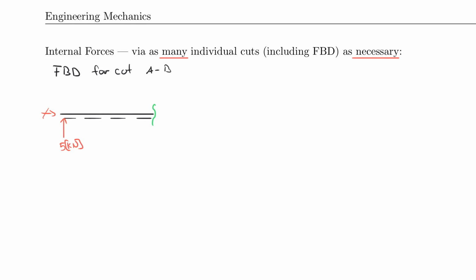But then there was no other force on the system. Remember that? There was no force except that one. And what I do next is I will bring in my internal forces that therefore become external forces. So for example, I use my little study card, which tells me that the moment goes in this direction, the shear force in that direction, and the normal force goes in that direction. So I now indicate them, and I call them M at B, V at B, and N at B.